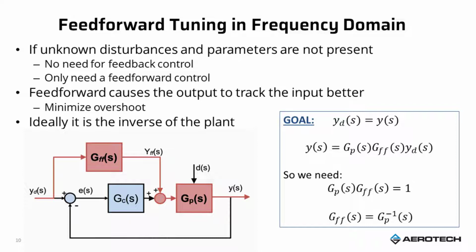So the feed forward really is the most authority in the loop. The highest current should come from the feed forward. And the feedback is really to accommodate these things we don't know about the plant: the parameters, the structure, maybe the resonance structure, and some of the disturbances that will occur.